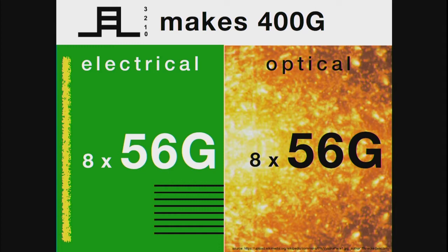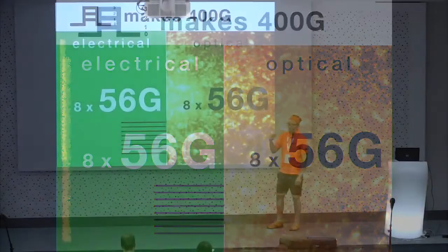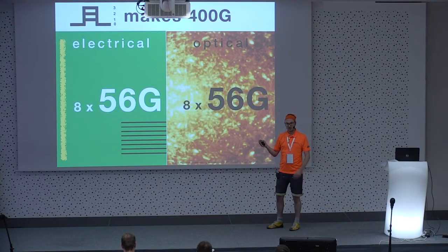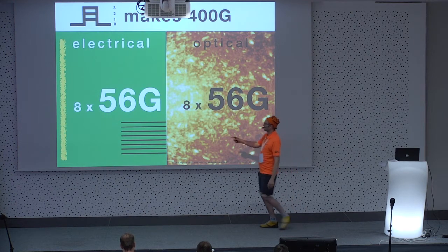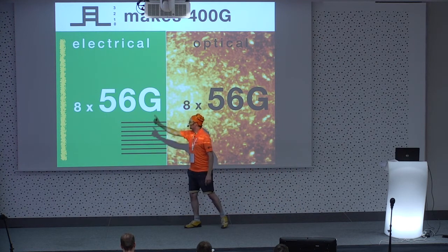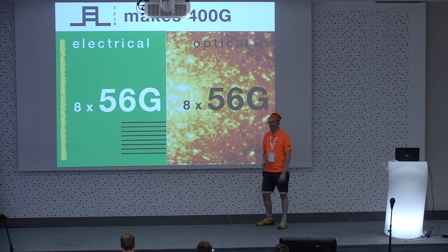Now for 400 gig, we need something more fancy, and when we use PAM4, we can double the density on the signal up to 56 gigabits because we modulate 2 bits in there. Double the data rate to 56 gigabit, and we would have 4 lanes, would end up 200 gigabit, but we want to reach 400 gigabit, so then it's pretty simple math. We increase the amount of lanes, and that's what we see here. So we got 8 lanes on the electrical side, talking to our host, and also from our host to our transceivers, doing 56 gigabit.